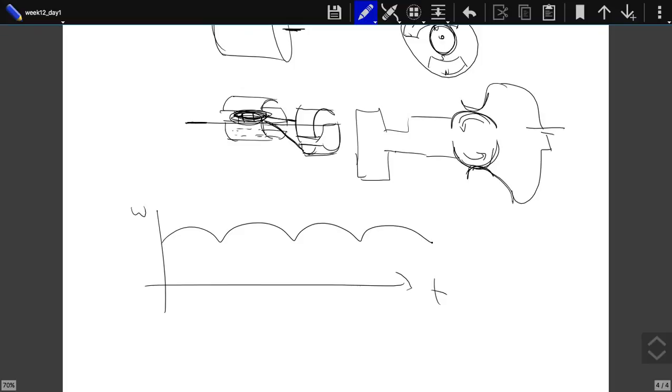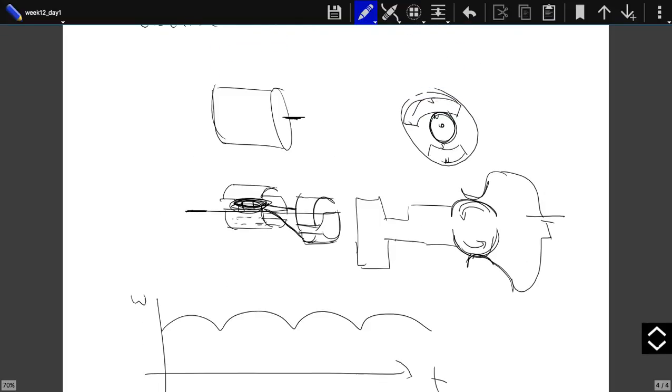Furthermore, you have to make sure that it is matching even if there is a load on the motor. That is, there might be some friction acting on your motor which slows it down, or some weight that the motor should lift. So it might slow down your motor, accelerate it, etc. Now, in this case, the synchronization between the motion of the motor and the changes in the direction of the current is done automatically. They are always in sync. If the motor doesn't rotate, then there's no flipping in the direction of the current.